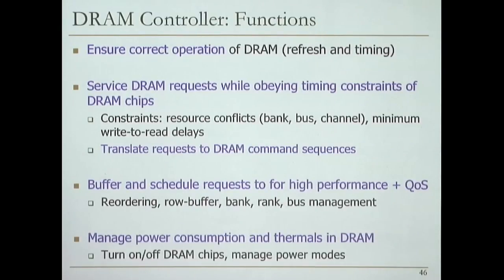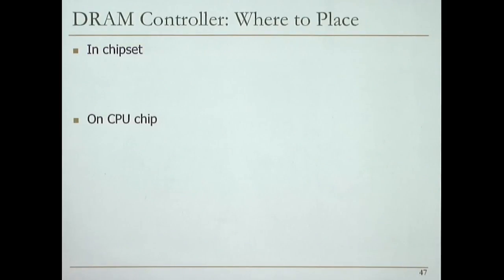And on top of that, modern controllers try to manage power consumption and thermals. You can turn on or off DRAM chips or ranks, depending on the granularity that DRAM provides, and manage different power modes. Make sense?